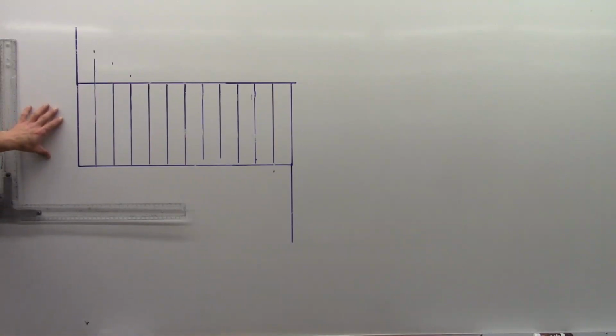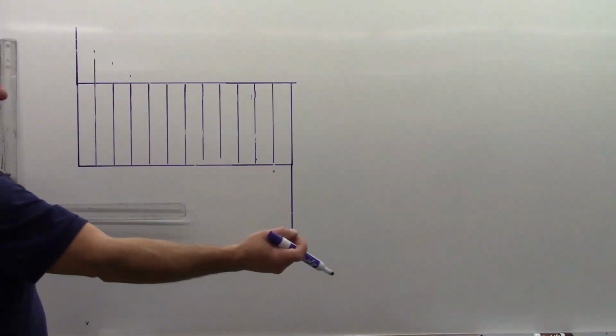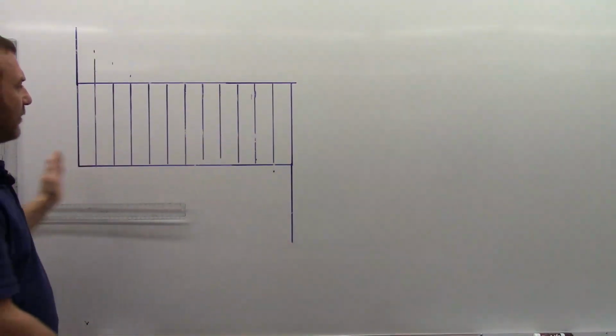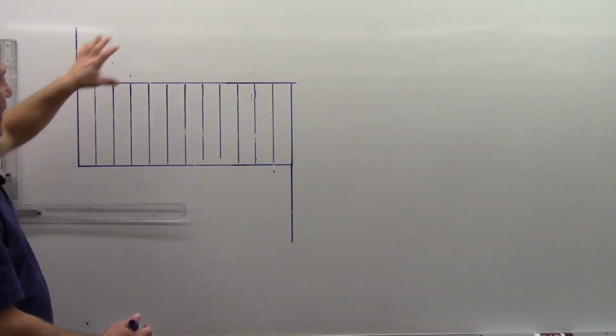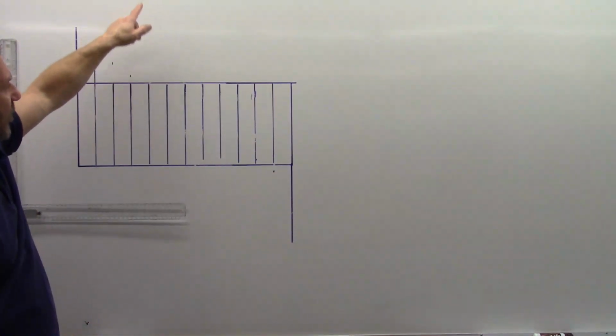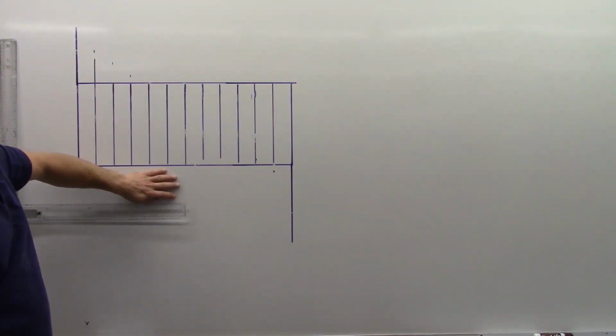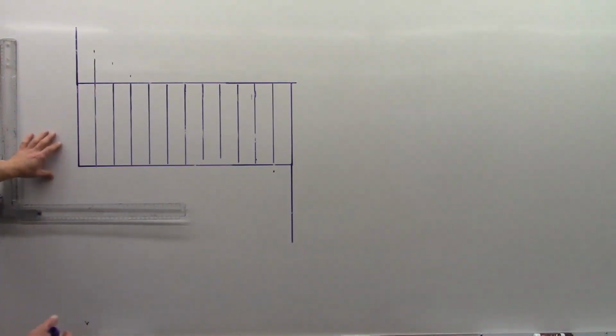Again, this one goes hand in hand with dividing a circle into 12 equal parts. Because when we take that circle and we stretch it out, it becomes a flat rectangle. Even a piece of pipe starts as a rectangle. And the numbers that we had, or the layout that we had on the circle in 12 parts, has to match the layout that we have on a flat piece of metal as 12 parts. So very commonly used. Again, elbows, T's, any round object like that we're going to make.